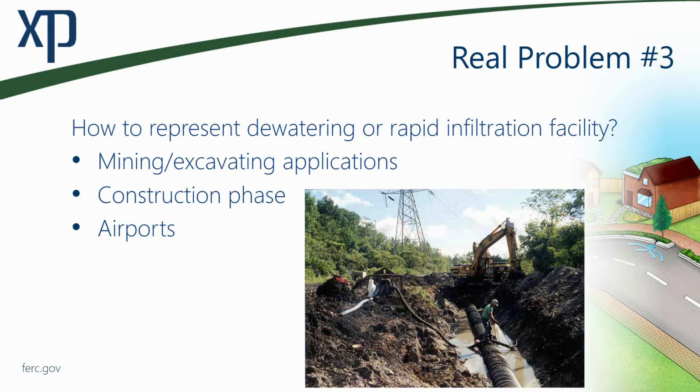There's that large pervious pipe, looks like maybe a 2-foot pipe, maybe 3 foot, that's laid down in that trench. They're going to maybe bury that with some sort of porous gravel, let's say, or maybe just leave it open like that. And ultimately, you're going to pump it out and draw that water down. That's what we're talking about here.